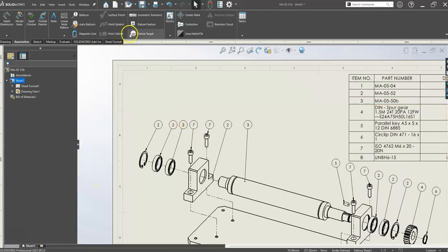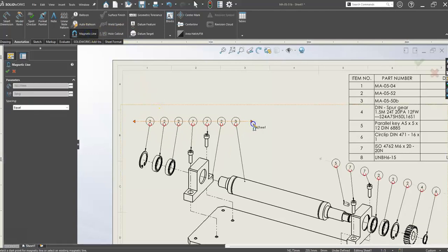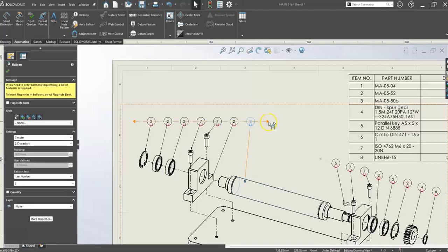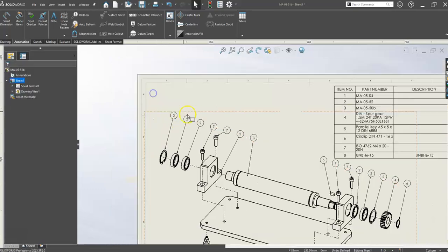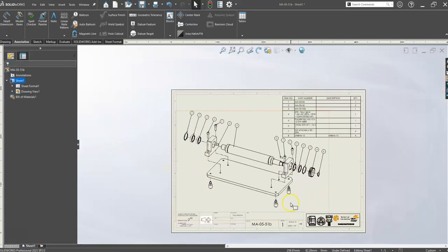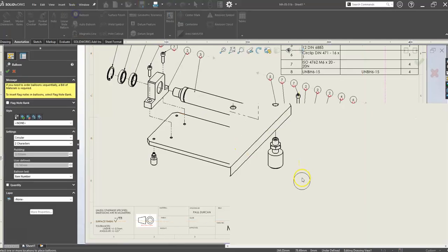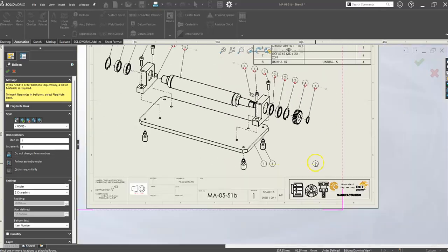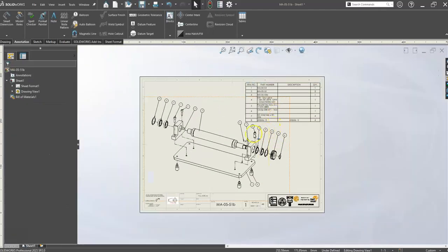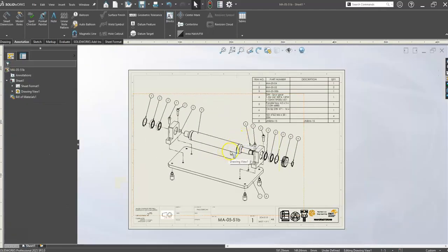And same up here, let's tidy these up. So we magnet line. Okay. Get the spacing about equal for both of them. Just play with it by eye. And again, you can line these up so it kind of snaps so they're in line with each other. That's kind of a good way to do it, and you can finish it off. I probably don't have all the parts there with the base and with the foot pad as well. Okay, so this is an exploded view of the assembly and how we do it in 3D and how we do it in 2D.